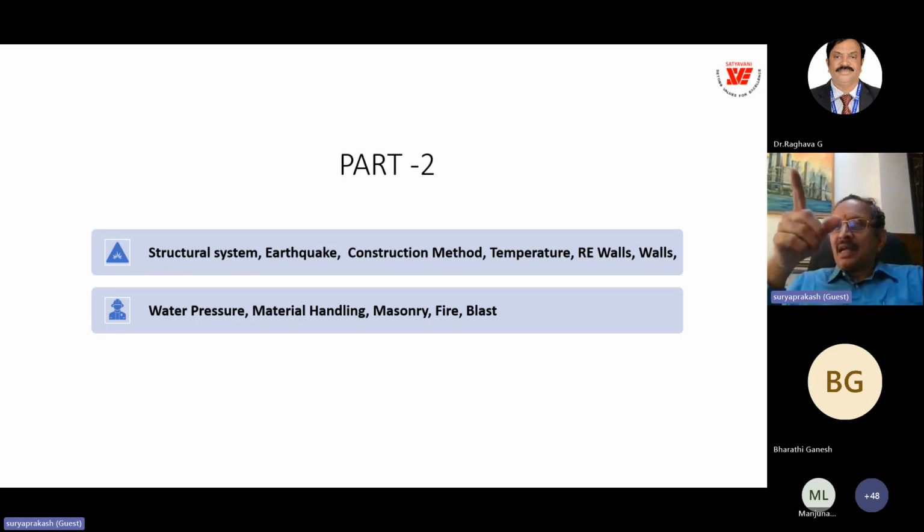And they exactly come in a diagonal direction from the column. But we check the levels, everything, and we found that the levels are also perfect. There is no deflection really in the slab, because without deflection you cannot have a crack in a yield line pattern. But we found that these shrinkage cracks have followed the pattern of yield line. It's an interesting observation.